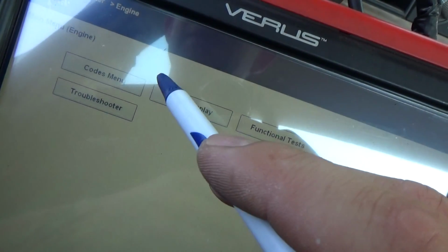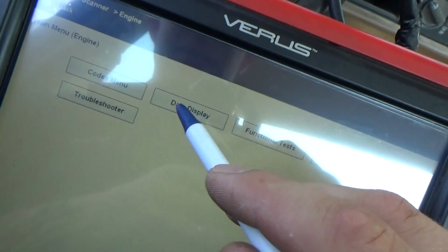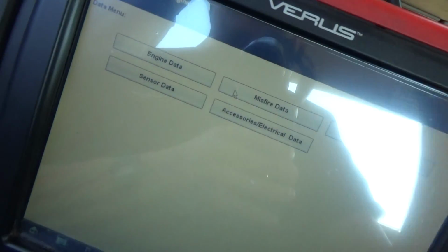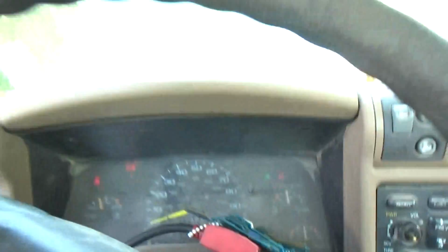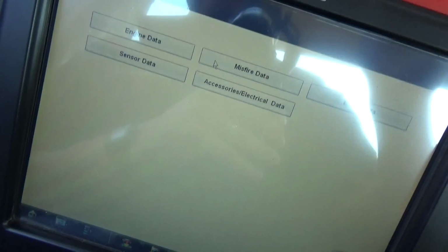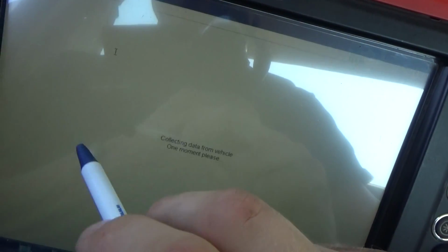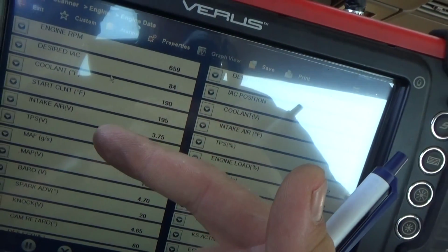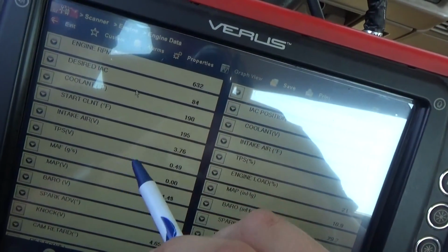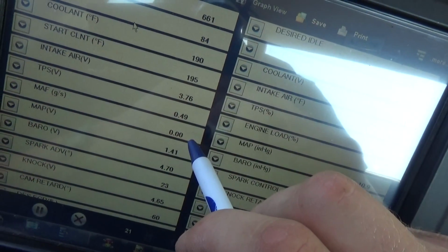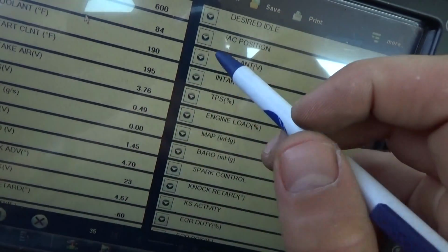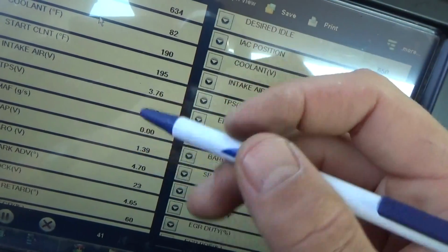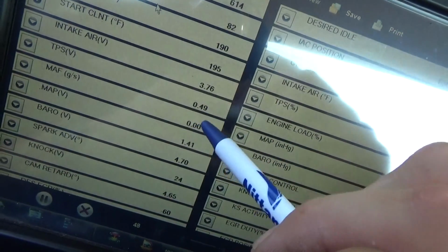And the truck is not really misfiring, but it's kind of lopey and not running quite right. You can see the fuel level. I don't know why that code's set. Maybe it's a history code. So engine data. We'll go for mass airflow and camshaft position. Mass airflow grams per second is 0.00. That's not good. Yeah, so okay. We have no mass airflow sensor signal reaching the computer.